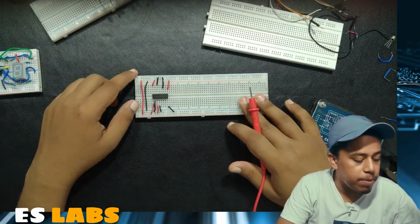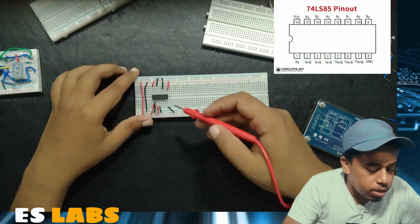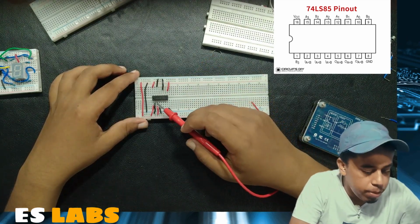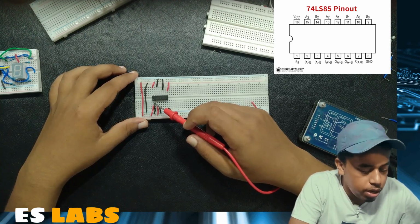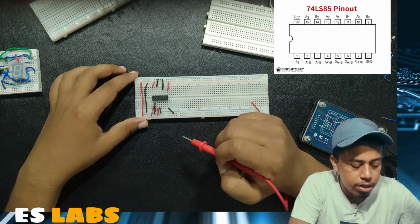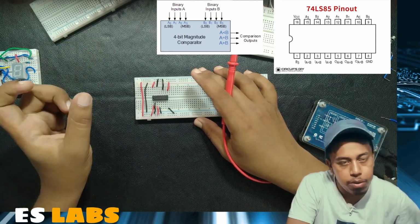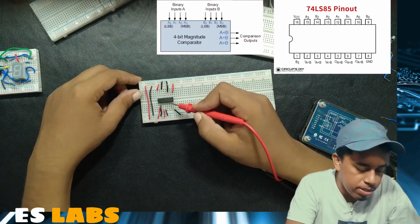So this is IC 74LS85. Pin 16 is VCC, so I have connected it through the red wire, and pin 8 is the ground. Pins 2 to 4 are input pins. Pin 2 is going to ground, pin 3 is going to VCC, and pin 4 is going to the ground. This IC basically compares the inputs A and B, which are A3 to A0 and B3 to B0, and displays the output at pin 5, pin 6 and pin 7.